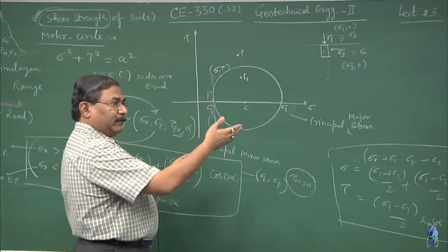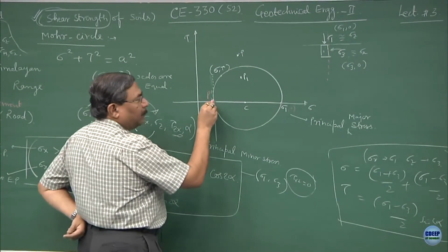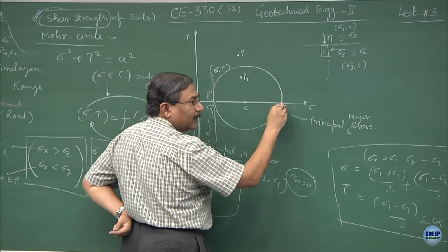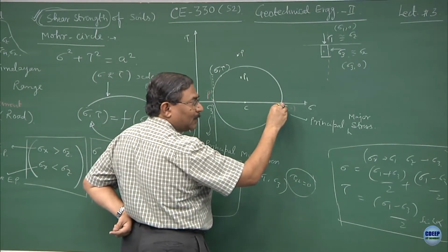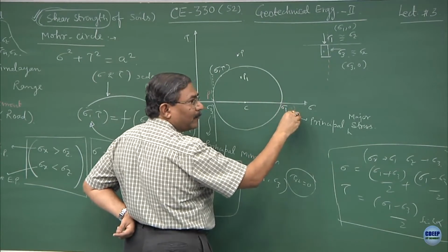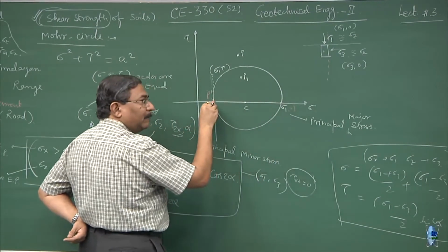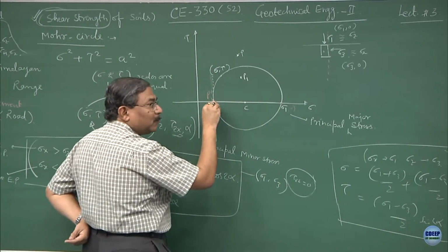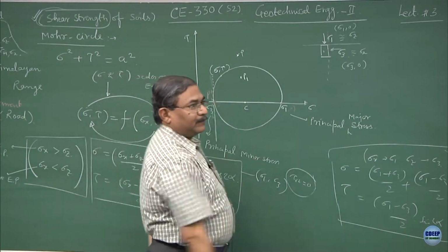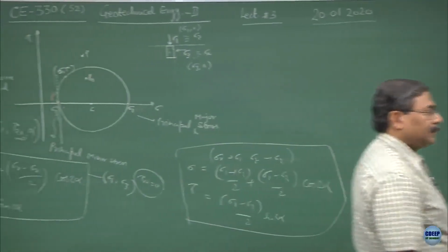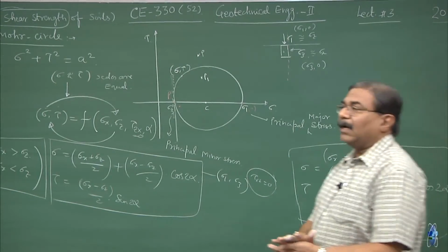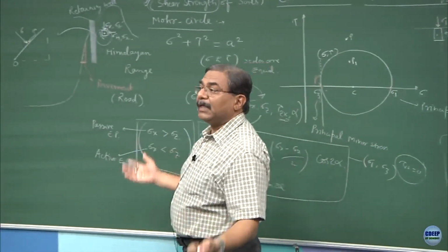Reverse what we discussed just now: starting from the pole, if I draw a horizontal plane, it is going to cut the Mohr circle over here, clear. So, this becomes your sigma 1 0. Starting from this pole, if I draw a plane which is perpendicular, it is going to cut the Mohr circle at this point itself. This becomes your sigma 3 0. Is this part clear? Please understand this clearly, because henceforth I will not be discussing this, but I will be utilizing this whole thing.